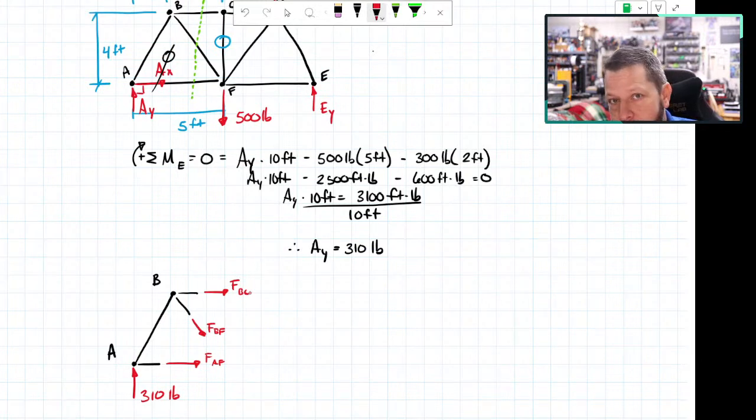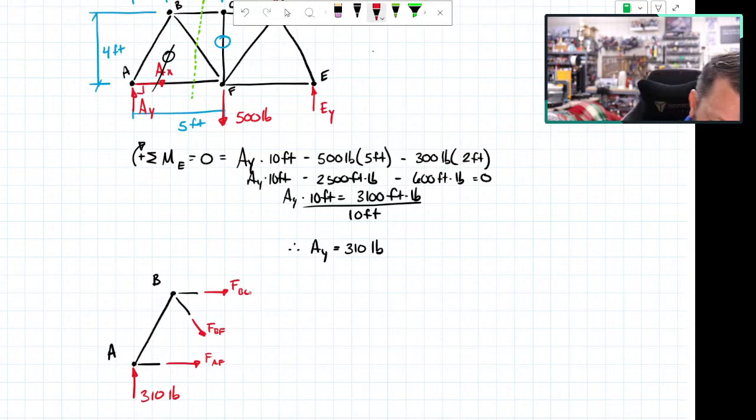That's just probably the easiest way to deal with it until you can look at a truss and say, oh, member BC is in compression based on this loading configuration. If you can do that, that's fine, and just draw it the right way. But it probably takes a while to look at it and just tell where things are tension and compression. So why I recommend, if you don't know, draw them in tension. That way, when you solve your equations, all the positive values are tension, and anything that came out negative is a compressive force. All right.